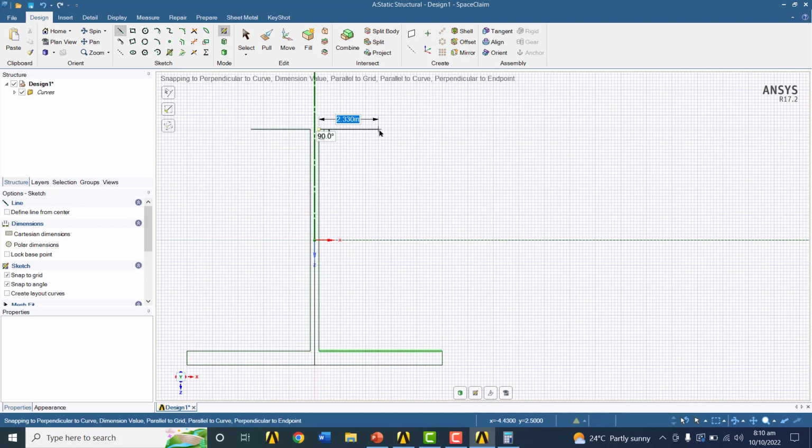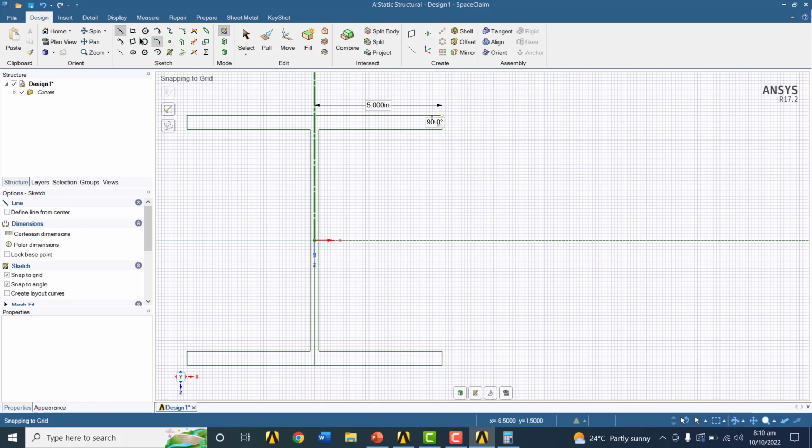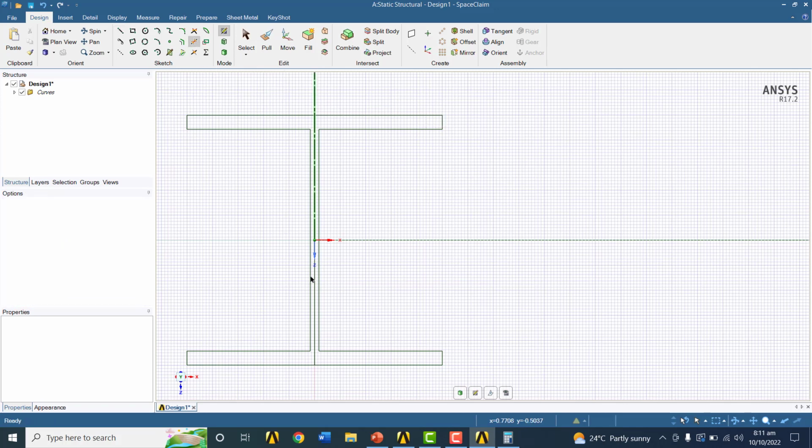So now we draw a horizontal line equal to the length of 4.83 inches. Press enter. Then a vertical line having height of 0.56. Then a horizontal line to finish our sketch. Press enter. So we will trim this center line. Press trim button, just trim away, and click on this line to trim, and our sketch is now complete.